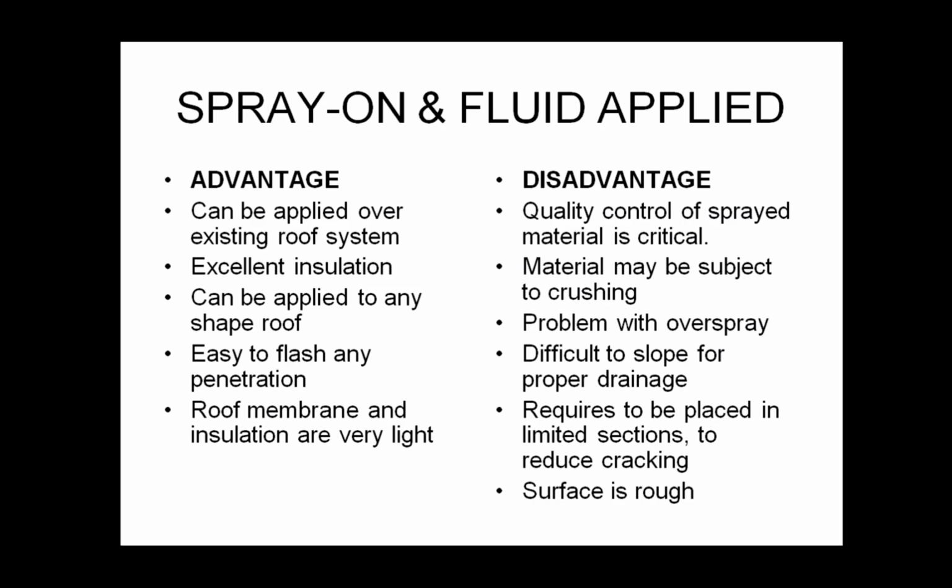This is sometimes difficult to slope for proper drainage, although it can be applied to any shape. It's very difficult to get that exact, consistent depth all throughout wherever you're doing it. So you're going to have peaks and valleys, highs and lows, places where things can pond.